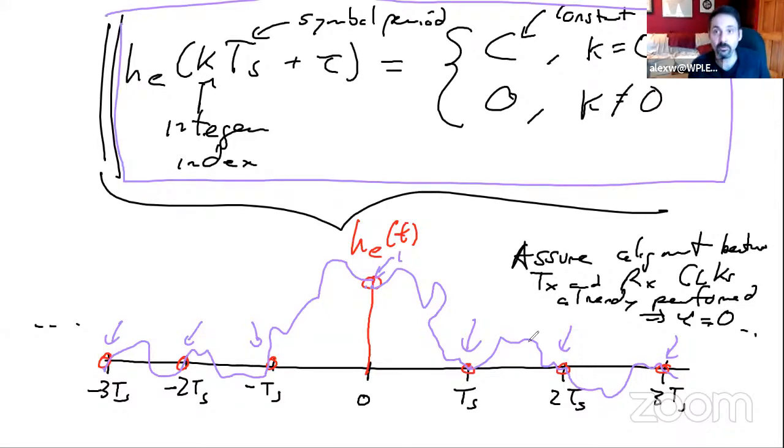What this means is, so what if the waveforms overlap with each other, like what we had before, because of the environment? What ends up happening is if I design a transmit and a receive filter, I have a channel filter, and I have my original pulse shape that results, let's say, from line coding, as long as the sampling instances that determine whether it's a 1 or a 0 are not interfered with, it doesn't matter what's in between them. And that's what the Nyquist pulse shape does.